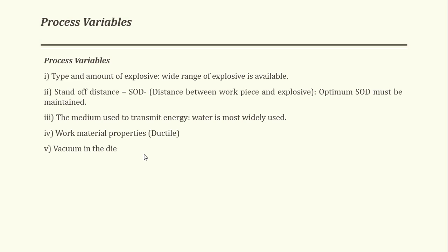Standoff distance: I told you the distance between the workpiece and the explosive is called the standoff distance, and it should be optimum. Optimum means as per requirement. Optimum standoff distance must be maintained to avoid oxidation or melting of the workpiece, or cracking of the die. The medium used to transmit the energy: water is mostly used as the energy transfer medium in this unconfined type.